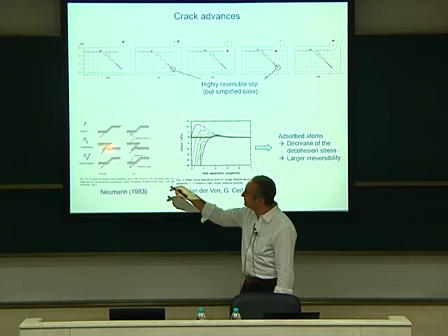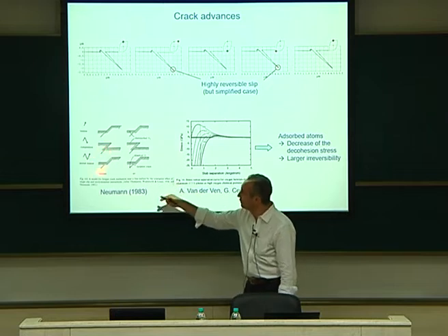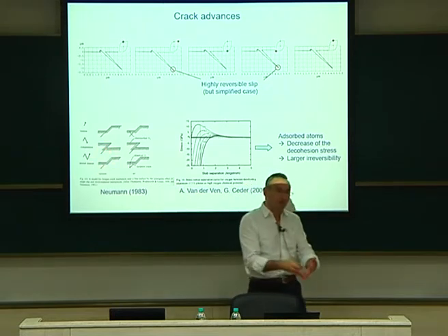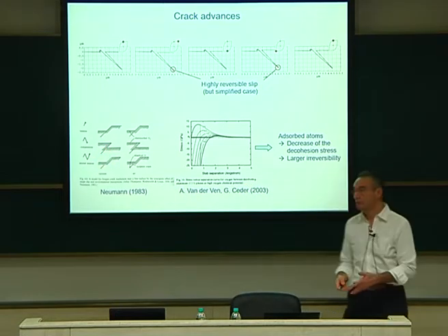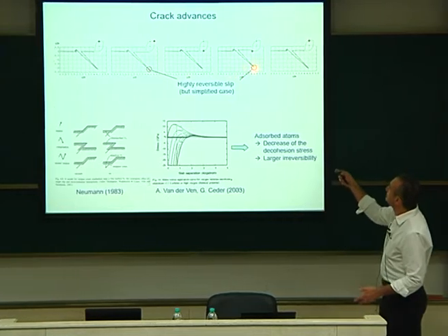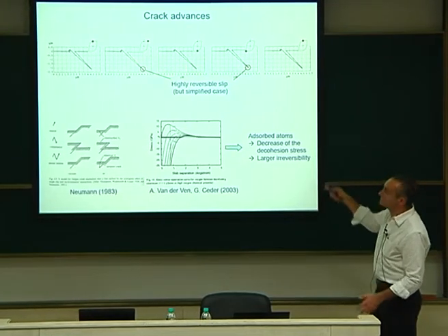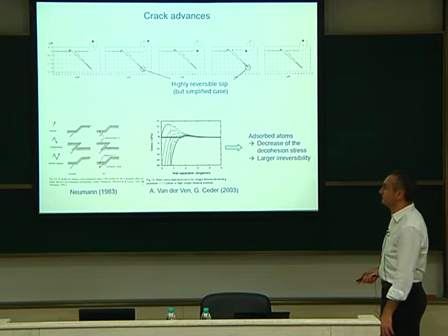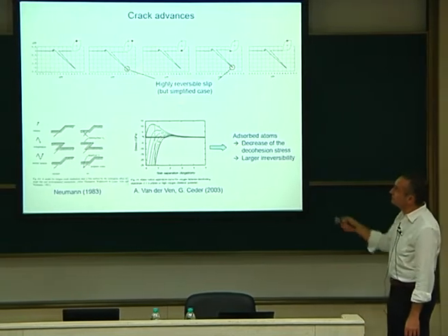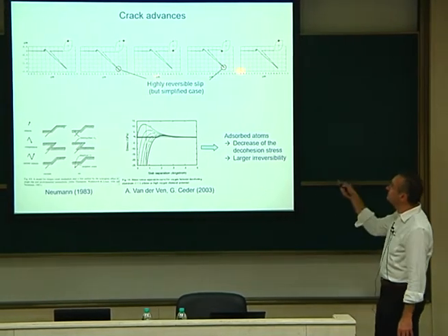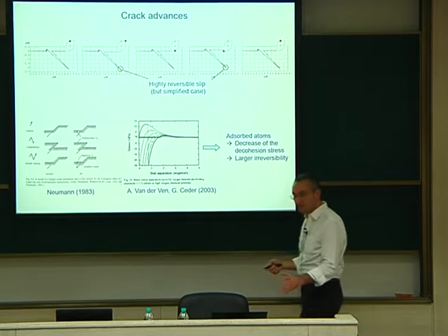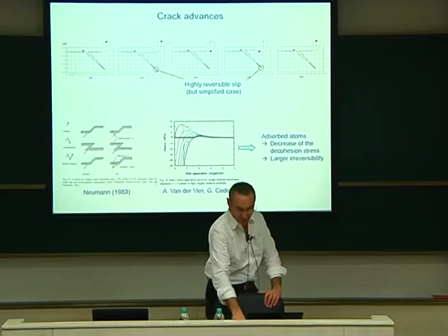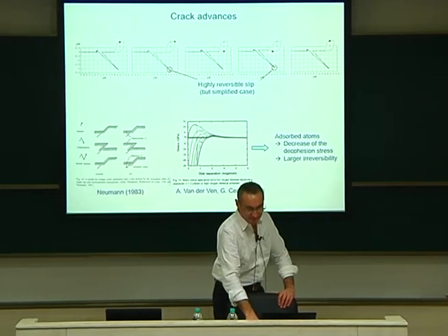Then when you unload, those oxides will be entered in your materials, and this will decrease a lot the cohesion stress of your material. So it means that in practice, these two steps, for example, are totally impossible. It's impossible to completely remove the crack, okay? So this is something that we should keep in mind, but in our model, this is, I would say, too kind for the material, too nice for the material, okay?